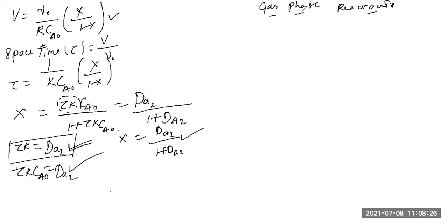It's important to look at the stoichiometry that we developed for variable volume flow reactors, because there we reached a relation where epsilon equals delta times YA0. We would be using this relation.